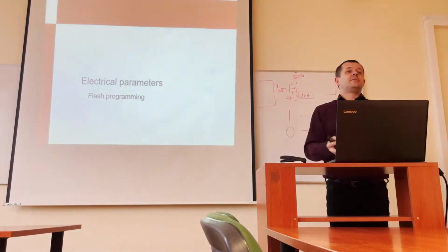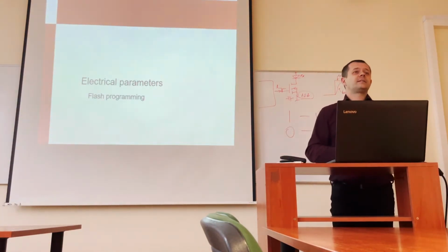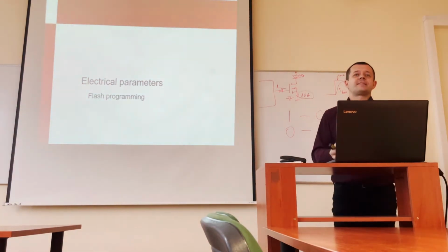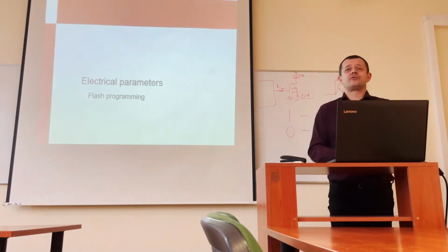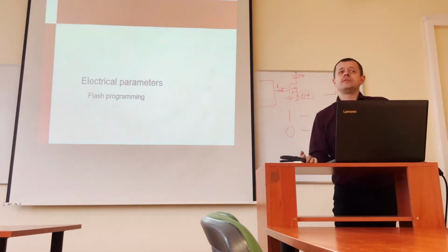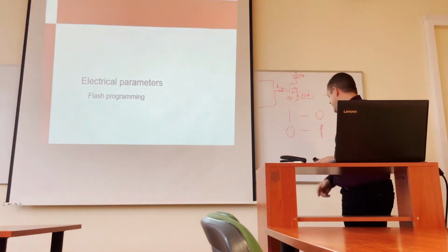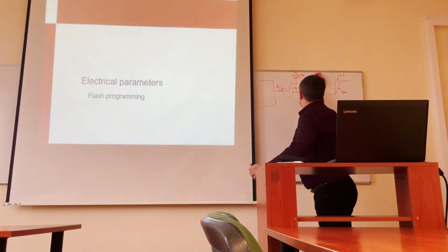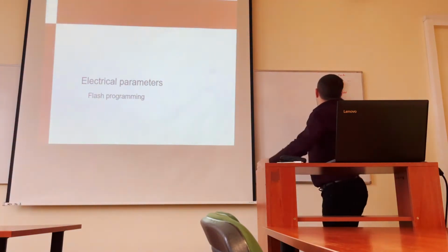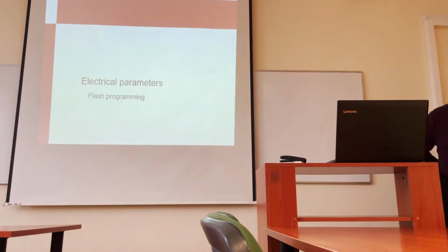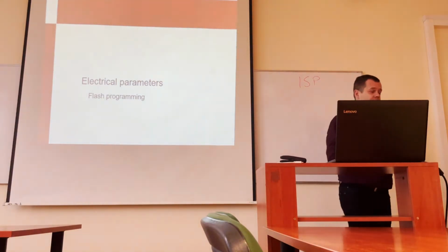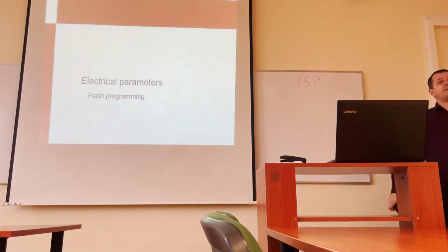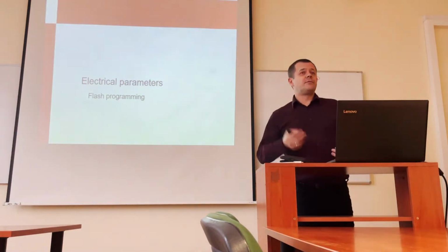The last thing, flash programming. We always have to connect some interface for accessing the memory of the microcontroller. Always. Today, there are no microcontrollers which are programmable outside of the system, which is actually good. So every microcontroller on the market that we can find today has the so-called in-system programmability function, called ISP, in-system programming. It became so common that today it's difficult to find a microcontroller without this functionality.